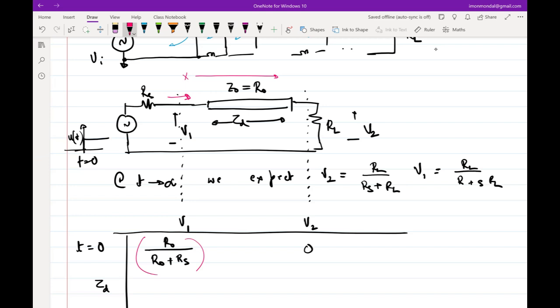Yes. Yeah, RS and RL are lumped. What do I mean by lumped? I essentially mean that there's no delay to go from one terminal of the RS to the other terminal of the RS, so a negligible delay with respect to the frequency of interest. Good point. That's why we are not bothered about what happens between the wavefront on the left side of the RS and the right side of the RS. They're identical. So that's the assumption.